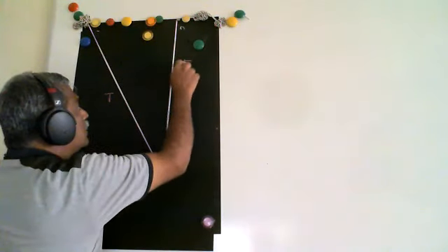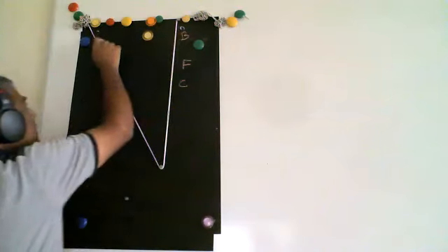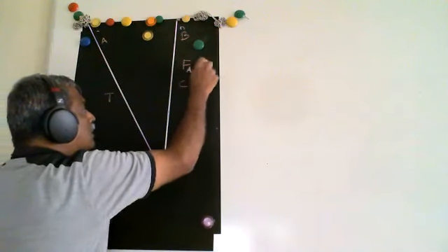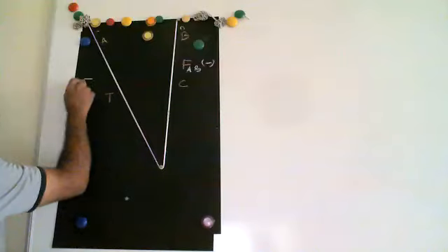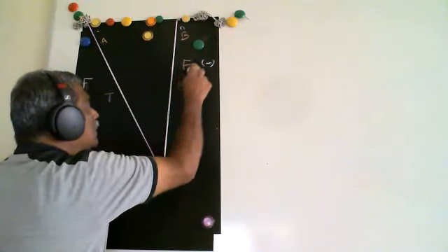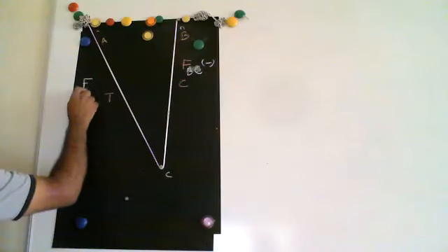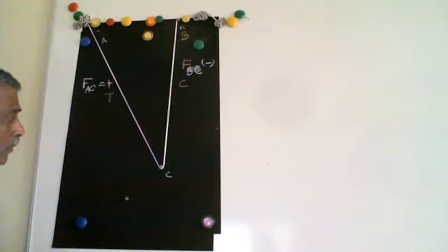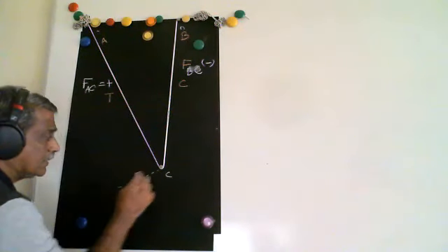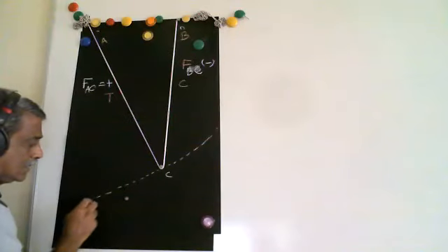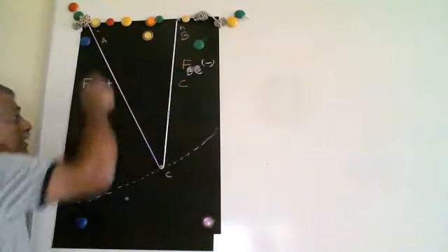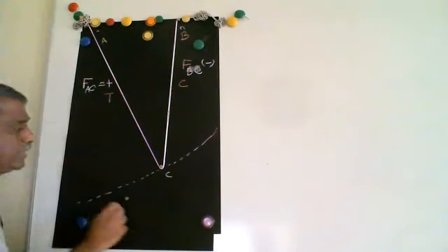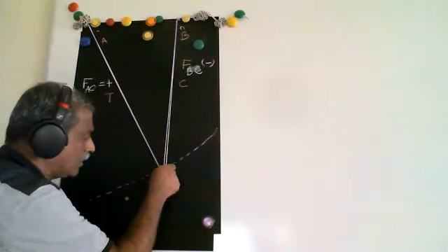So I'm going to call this B, this is A, right? FAB is negative. FBC is negative. FAC is positive. So what should happen now? If I have, let's say, this is the initial curve as I swing this AC, it has stretched now because this is in tension. So let's say it has stretched like this.